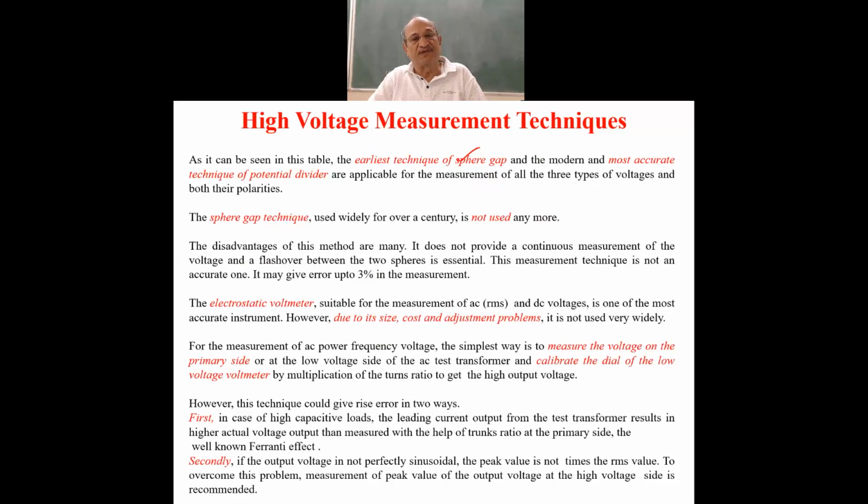For education purposes, you can produce a nearly uniform field for a small gap distance, with sphere gaps having very large diameter, and you can experiment. You can measure the breakdown strength, and students would like to perform the experiments and measure, and consistent results are there. So that can be used for high voltage experiments to be done by the students.